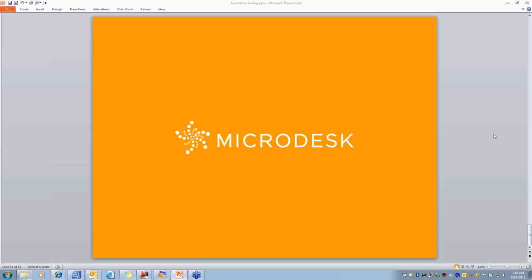That tool will allow you to clean up multiple drawings at the same time, whereas if you individually go in and edit the scale list, it's one drawing at a time. But if you find that you have drawings where those scale lists are there, that cleanup scale utility will allow you to do it with multiple drawings.